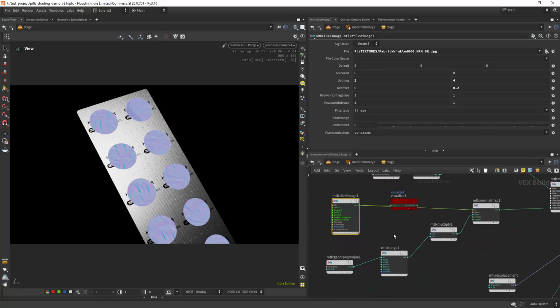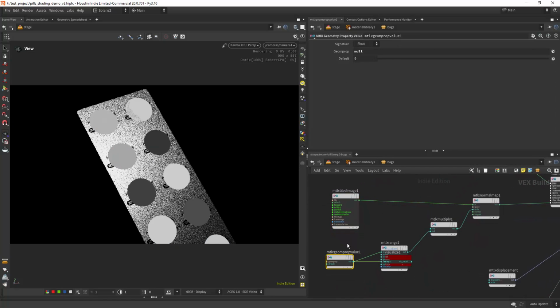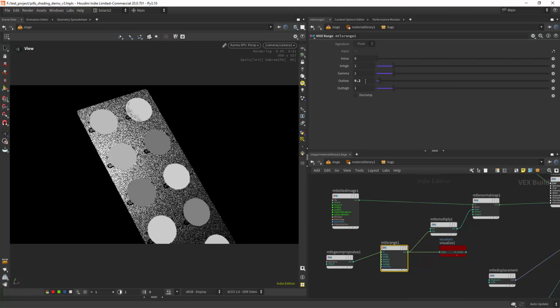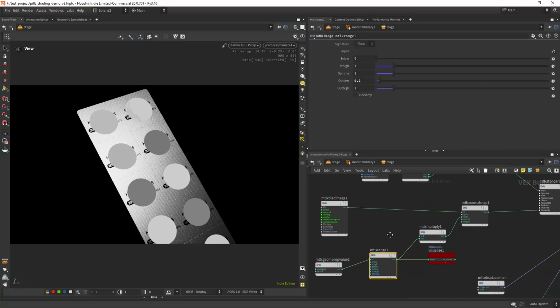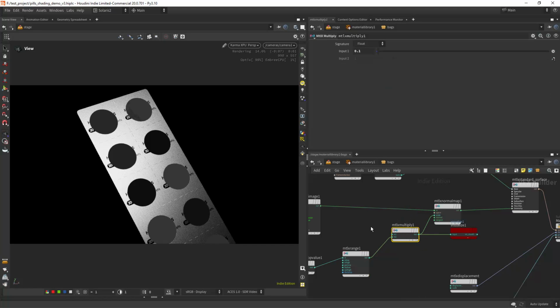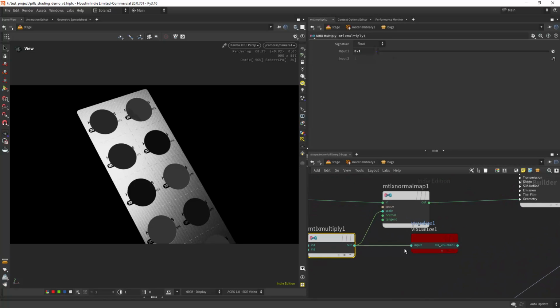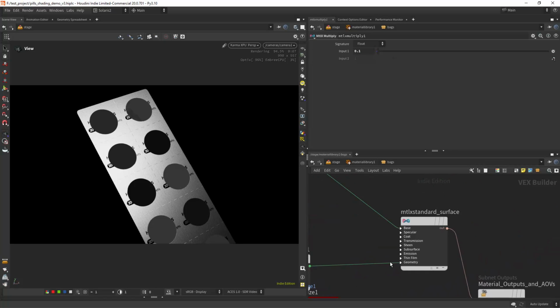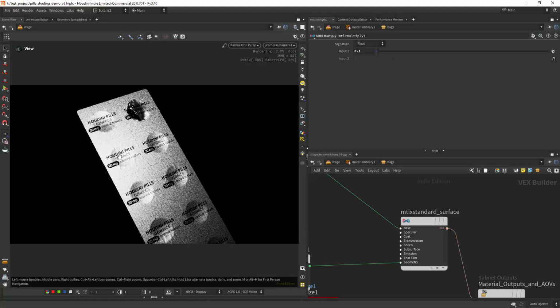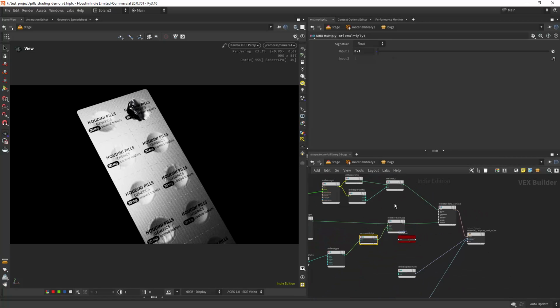And I also have an attribute that I'm fitting in a range, so increasing a bit the low and multiplying by a scale value that I'm feeding to the scale of the normal map. And at the end I have some parts that have more wrinkles and others that have less, based on an attribute.